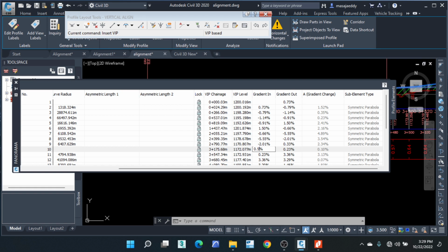At least it's more than 0.5% in the areas of the swamp. Even in the swamp region, that's why I'm adjusting, but even in other areas of the road, it just has to be more than 0.5%. In areas of fill, whether in fill or in cut, it just has to be more than 0.5%.